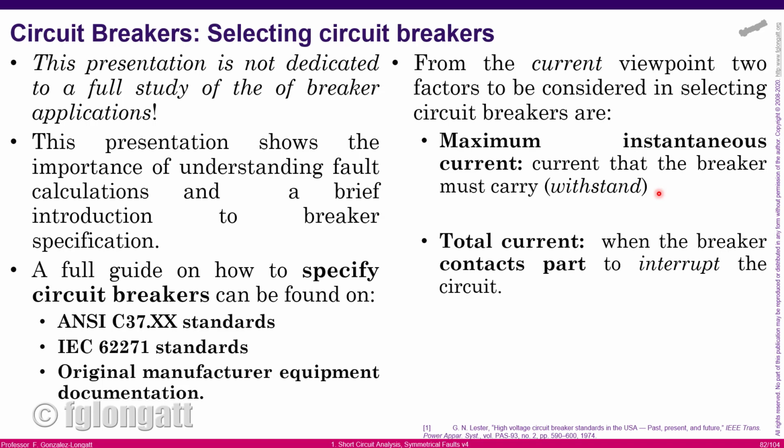But then there is a protection relay. It will take some time to operate. It will send the signal to the breaker, and the breaker must open the contacts. As you can see, there is some time involved in this action, and this time is mainly related to the operating time of the relay, that today, with the use of modern digital technology, is extremely small.